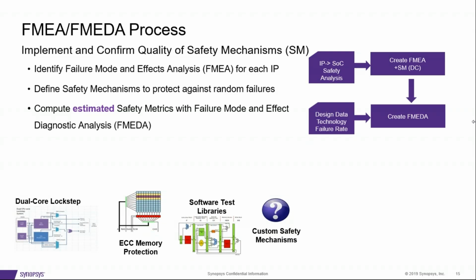But typically it's going to be based around the idea of redundancy, duplicating logic such that you have more than one answer and they all have to agree. If they don't agree, something has gone wrong, and you can use some voting mechanism to decide what to do. Is it stop the device completely, or try again, or do something.